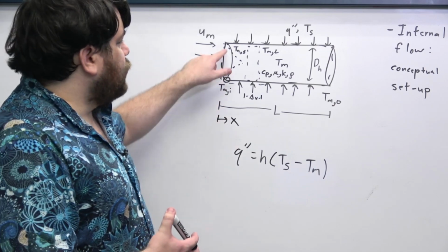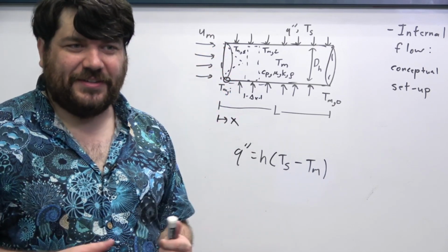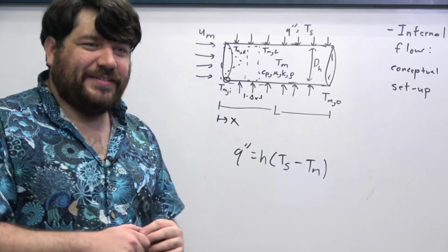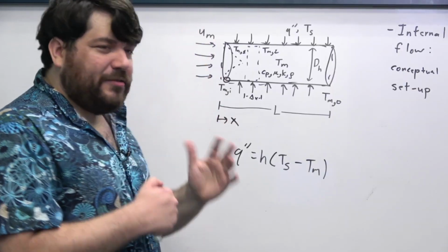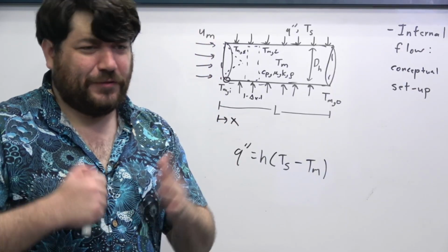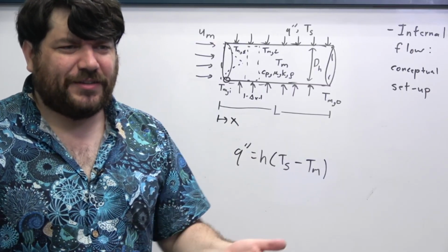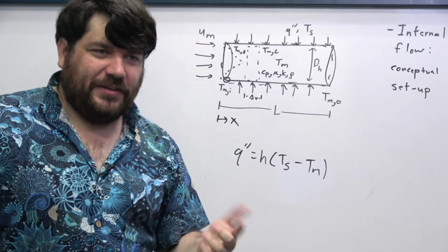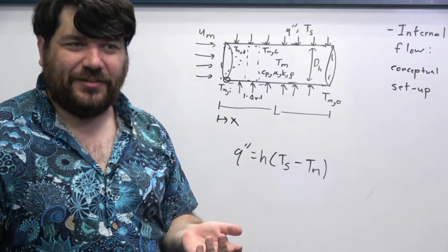But that boundary layer is also forming on the top end and on the sides, and it's a duct, so of course it would. Eventually, because this liquid is no longer semi-infinite, those boundary layers collide. And so the notion of a boundary layer goes away, because now there isn't a specific region in space over which the fluid characteristics are changing and over which they're not.